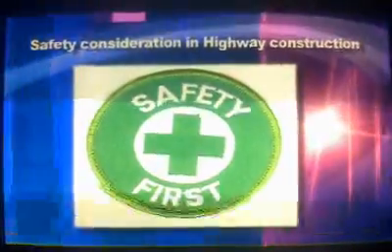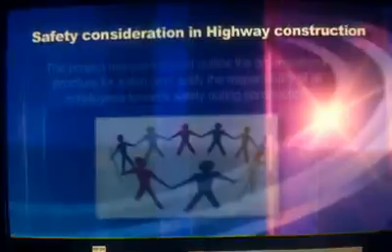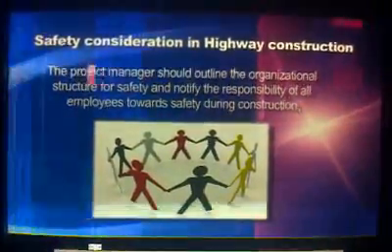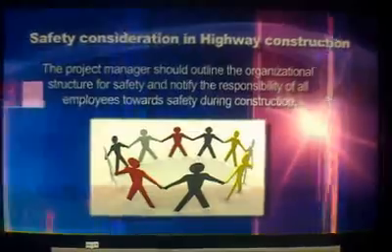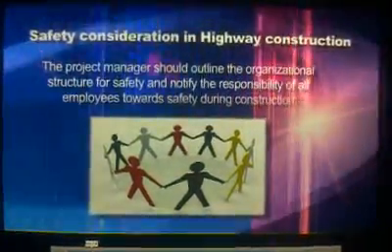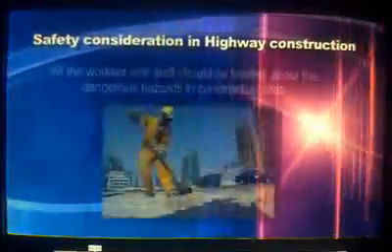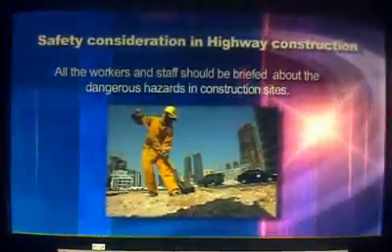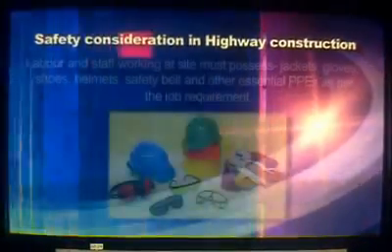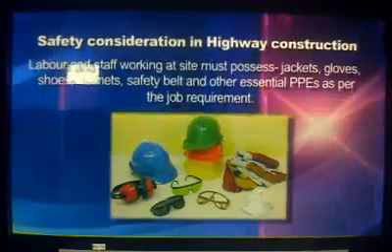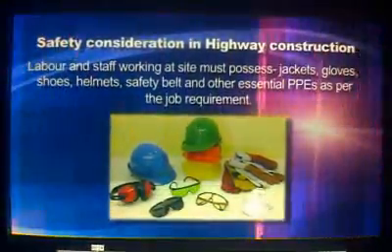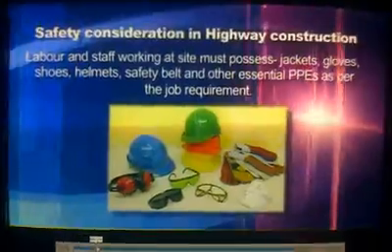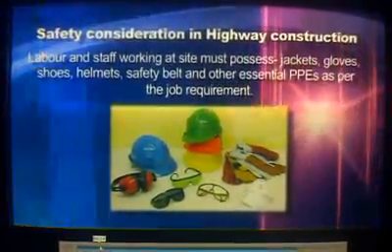Safety consideration in highway construction. The project manager should outline the organizational structure for safety and notify the responsibility of all employees towards safety during construction. All the workers and staff should be briefed about the dangerous hazards in construction sites. Labor and staff working at the site must possess jackets, gloves, shoes, helmets, safety belt, and other essential PPEs as per the job requirement.